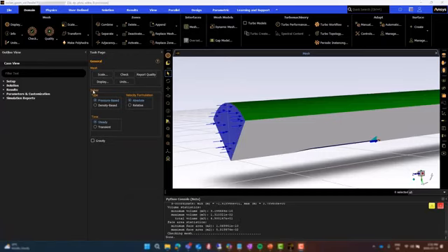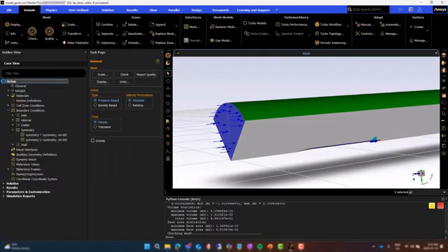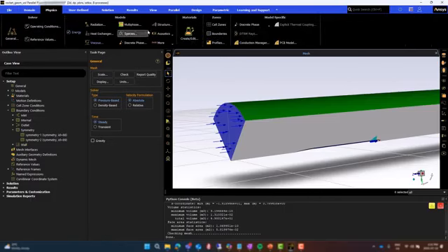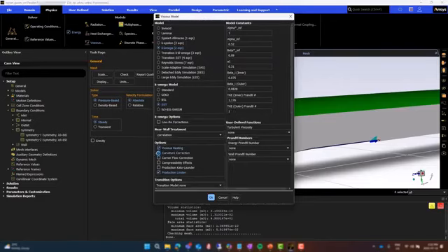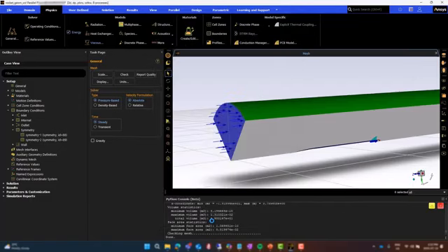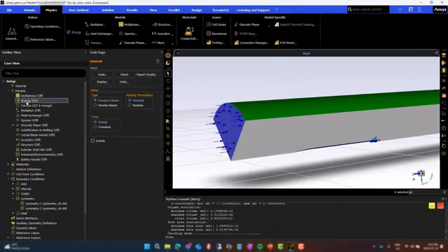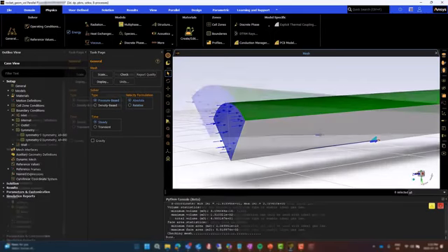To set up a Fluent simulation, we'll use the workflow tabs and work from left to right and progressively set up the simulation, solution, and results. The same workflow can be seen in the tree view on the left. However, we'll be using the tabs on the top. The first step is to select the pressure-based solver and steady time stepping for the steady-state simulation. Ensure the energy equation is enabled and select the K-omega SST turbulence model with viscous heating and curvature correction to accommodate the high-speed flow modeling. By navigating over to the settings tree, we can confirm the model changes carried through in all workflows.